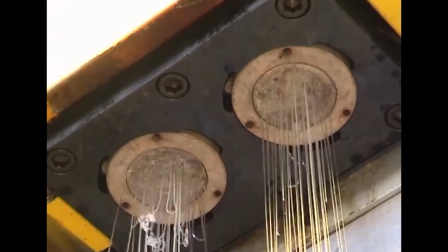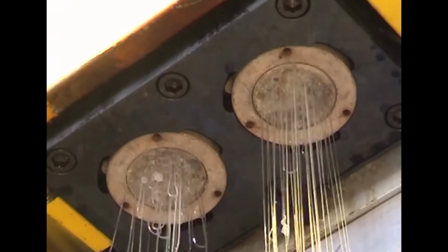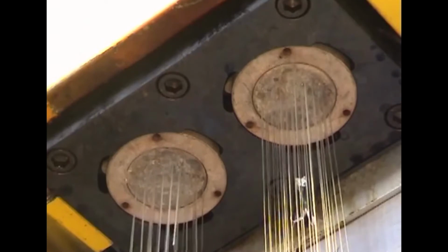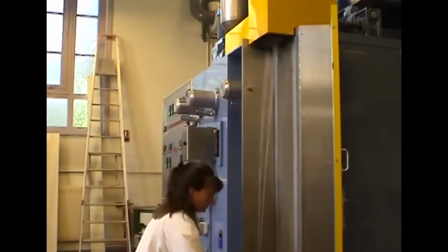It is called a spinneret, which is a small metal plate having fine holes. And so, the polymer in solution form is made to pass through the holes of the spinneret, and then it gets solidified when it comes out, and thus you get a continuous filament out of it.